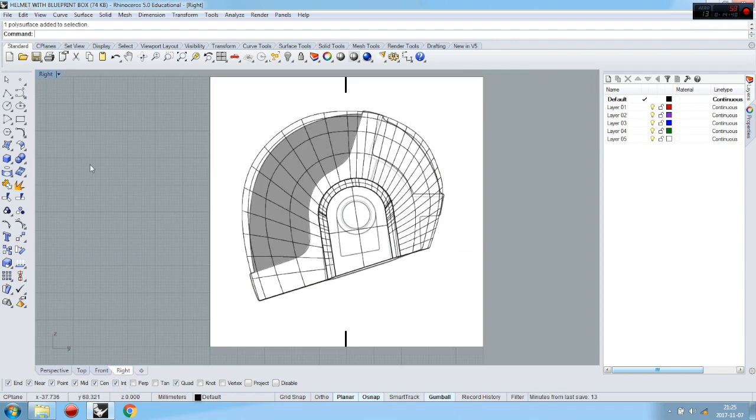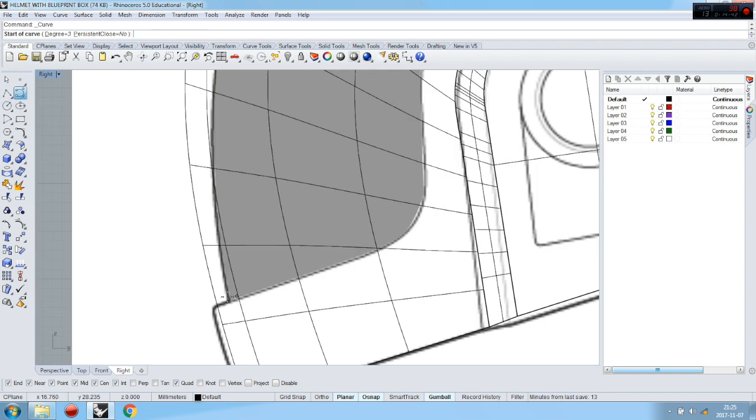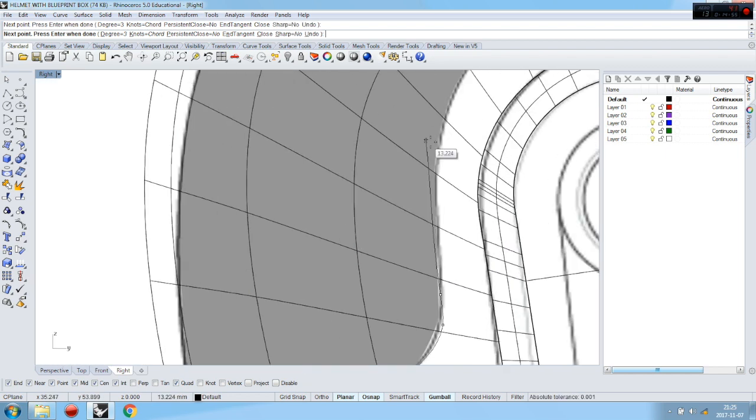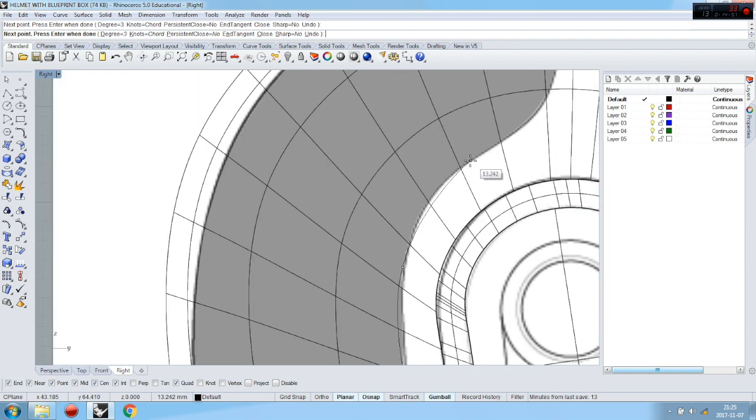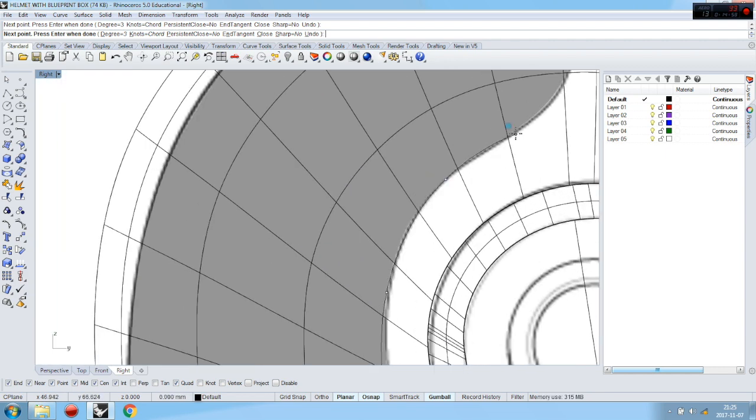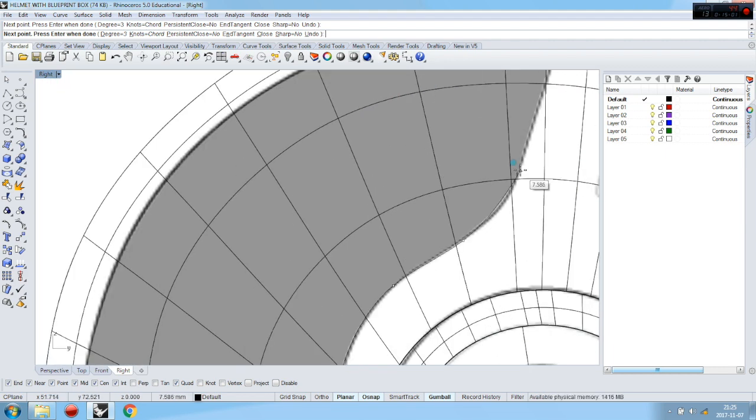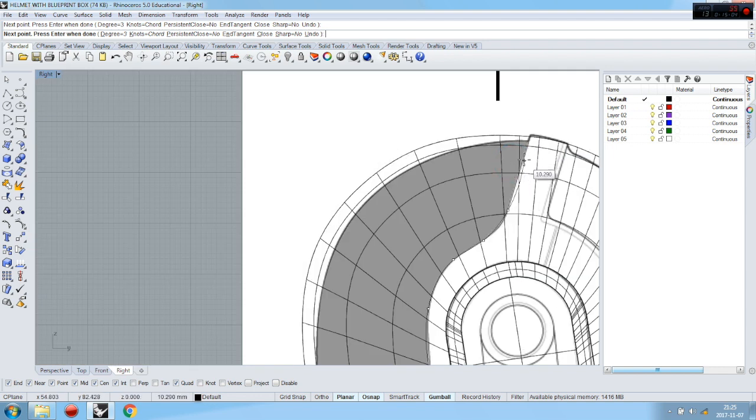So I'm going to create a control point curve. I can actually create an interpolate point curve because it's better, because it's just going on my sketch. It's much more precise according to the sketch I've got on my stage. Yeah, it's like that.